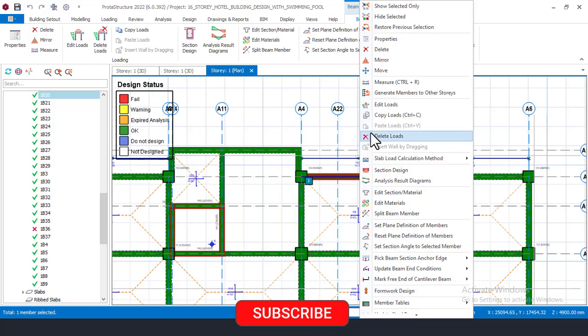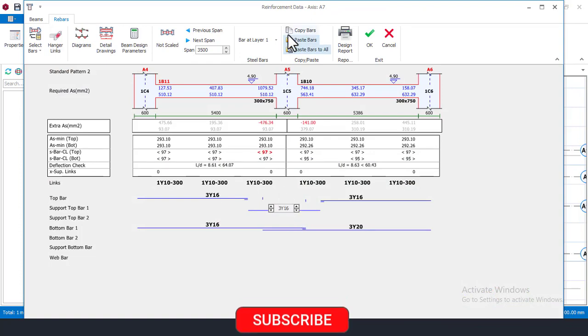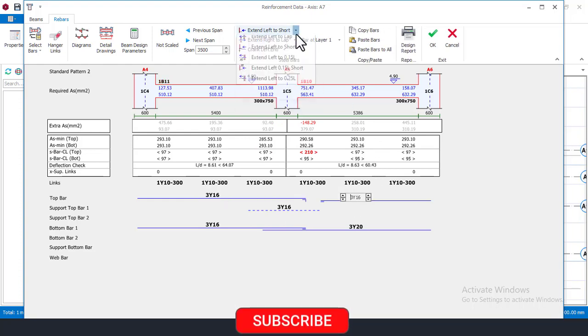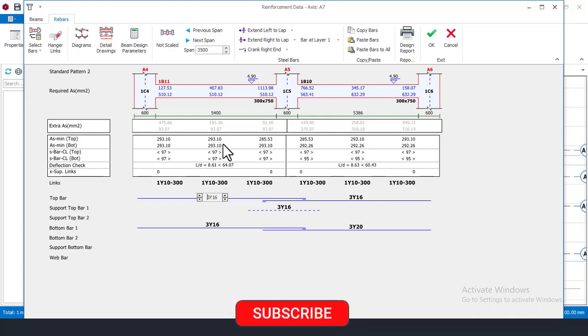Okay, so I'll come again right now and check again. This is that one, right click and then say Station Design here, and I'll come again here and just arrange my bars based on what I've done before. Reduce this to 16 and then make it layer 2, and then come here, lap this one into the column, lap, and then come again here, lap the reinforcement into the column again here, lap, and I'll come here, make it to be 4. I think we used 4 before, but I think right now the 3 at the top is still low, so I can choose to have 4. I think this is okay. Yeah, this is okay. 3 on this side is still okay.